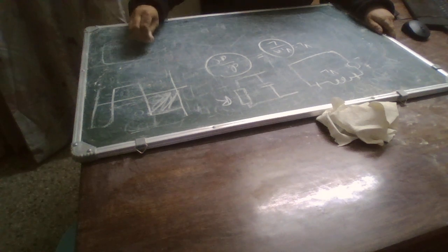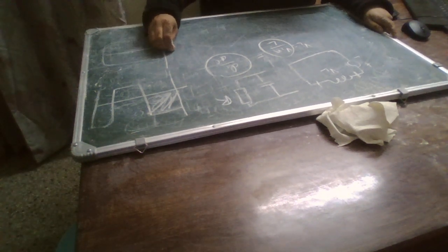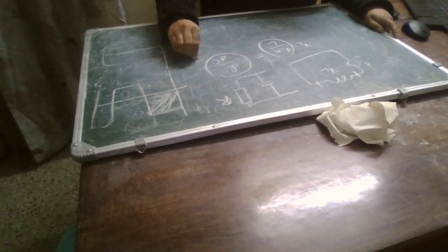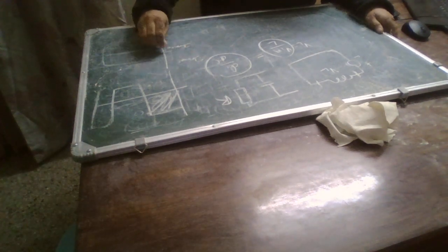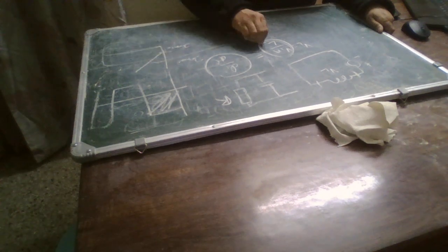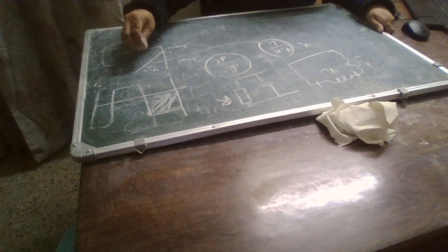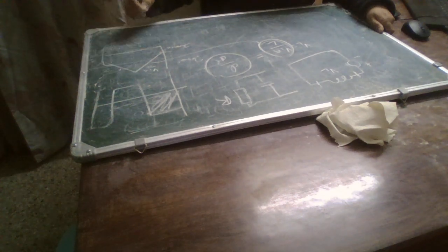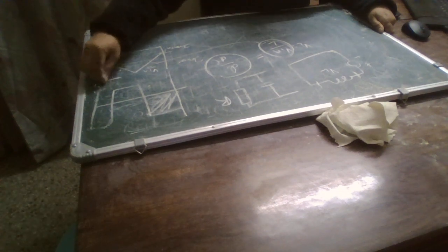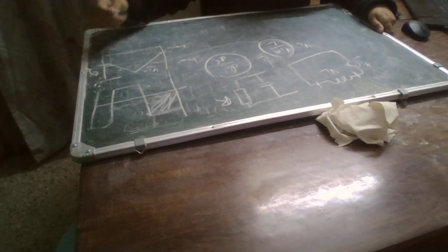Now if I am going to take the inductor current rise, I can say this is I minimum and I can put I maximum, and it's going to rise linearly. And this linear rise slope is what? V input by L. The slope here is V input by L. We will see during the t on time period what the slope would be, and the difference between the maximum and the minimum, let's denote by delta IL.